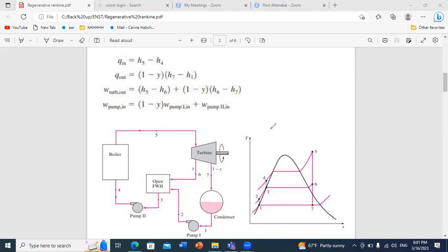So here, after I determine point 3, I will be able, as we mentioned, to determine state 4, because the relation between 3 and 4 is, as we discussed, that we can find the corresponding work by saying it's v delta P. Here it's P high minus P intermediate.